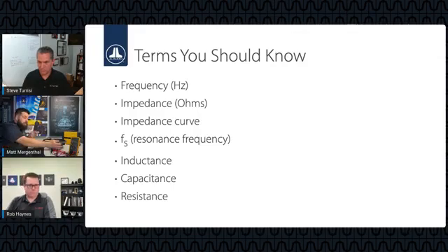However, if you measure a speaker like this one, the resistance will usually change depending on the frequency that you measure it at. Right below that, we have the impedance curve, and this basically just shows the speaker's resistance over frequency on a graph. Like I mentioned earlier, we'll jump into some graphs in a little bit. We also have Fs, which is also known as the resonance frequency.